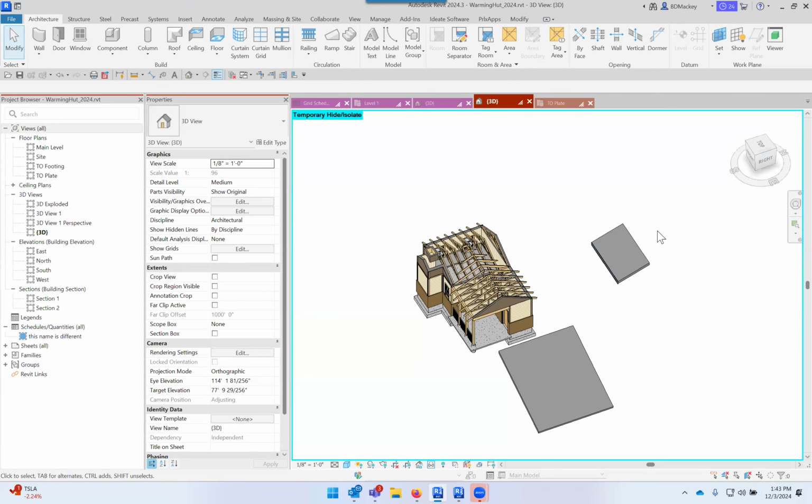Yeah, draw layout detail lines. But again, if you're trying to host to a dome and always be perpendicular to that dome, you've got to get a surface-based object. Layout detail lines just don't do anything for you when you're trying to host to a curving surface or a warping surface or anything.